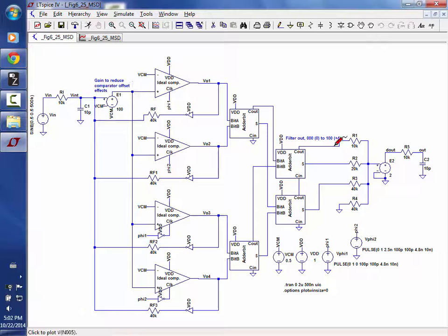So just as a sanity check for myself, what is this right here doing, these 4 resistors? Well, it's a digital to analog converter, right? This voltage, this current plus this one. So the LSB is weighted less than the MSB, so I get more current through the 10K. This is just a simple A to D converter, or D to A converter rather. Okay, so this is a DAC just so I can display the data.